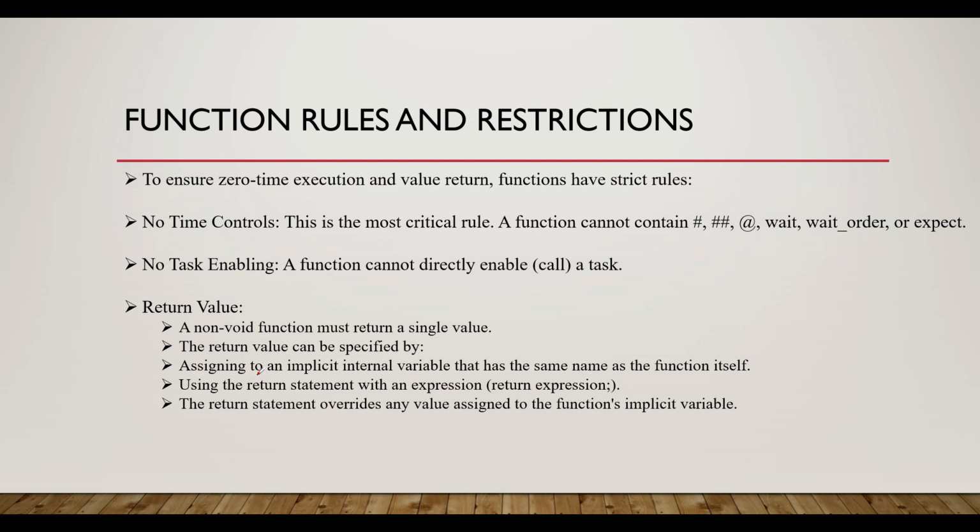So you are not allowed to use any timing control inside the function. Now, no task enabling. Since our task has a timing delay, you are not allowed to call your task inside a function, because your task has some time delay.